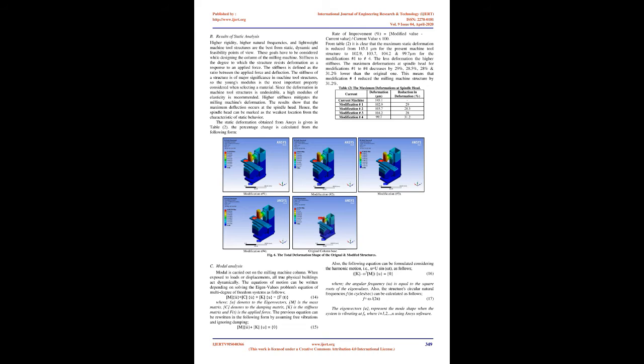The mass of the milling machine column is 1,175 kilograms. 165 kilograms is subtracted from the base of the column and added again in the form of honeycomb form to be reinforcement ribs added to the core of the machine column. The redistribution and the reshaping of the column are shown in Fig 5. The current height of the machine base is 130 mm. This height is reduced to 80 mm through the suggested 4 modifications. Figure 5 summarizes the 4 suggested modification scenarios.